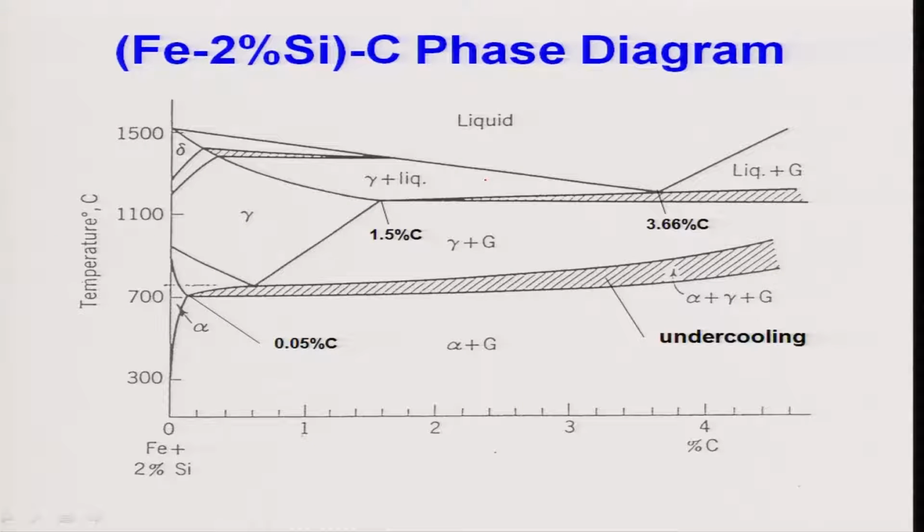Now, to explain that, I am showing you something new which you have not seen, or probably it is not in the books. It is better to plot a phase diagram which is called a pseudo-ternary phase diagram. Anyway, we will discuss ternary later, but this pseudo-ternary diagram is again temperature versus composition, there is no third axis, only two axes and a 2-dimensional plot, with iron with 2% silicon and carbon concentration varying, because 2% silicon is invariably present in cast iron.